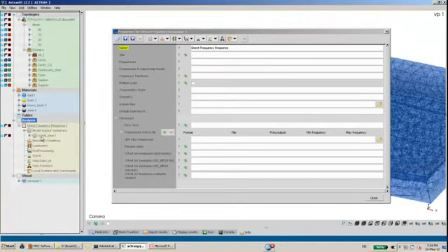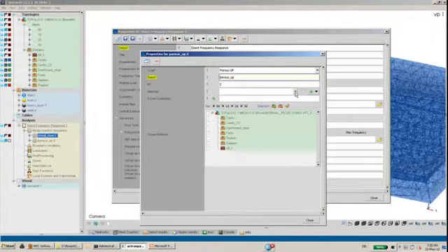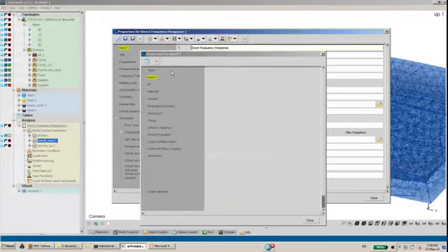So you see here now on the left-hand side, I have the component that I have just created that has appeared in the tree. So the next component I will create is the Porous UP component. Again, I need to point to the valid material, and I will select my foam domain. Then the third one will be my septum.